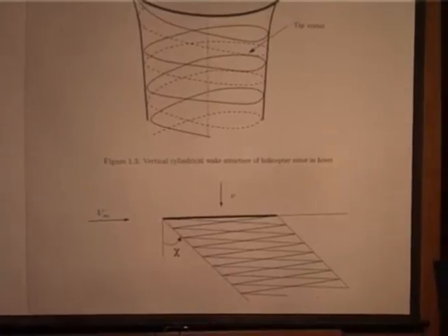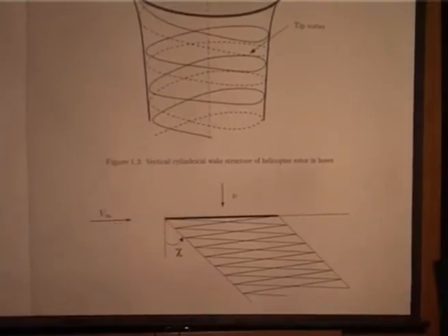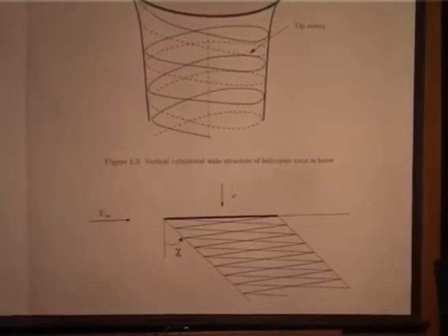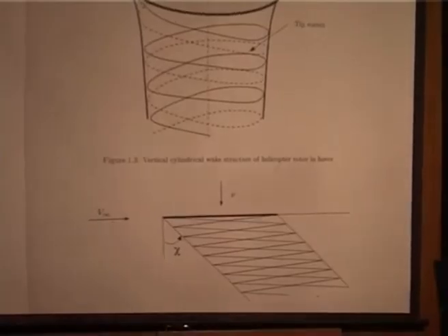In the sense, the wake is not completely swept behind the rotor disc, it is not straight below also, but it is very close to that, and then it is skewed. And this really complicates the problem, because the wake is close. When the blade travels, the wake from the front blade will come close to the rear blade. Usually you will have high vibration, etc. in that transition zone.